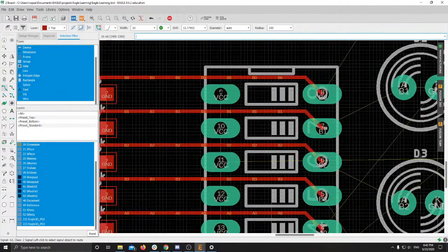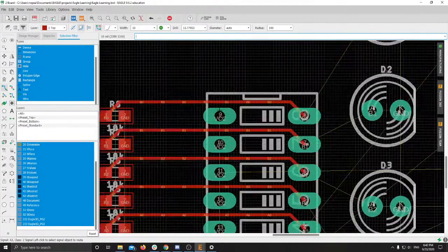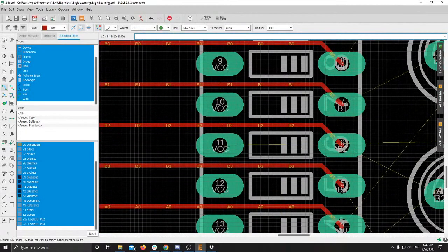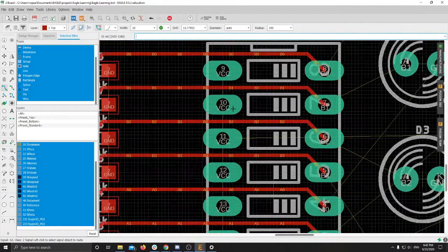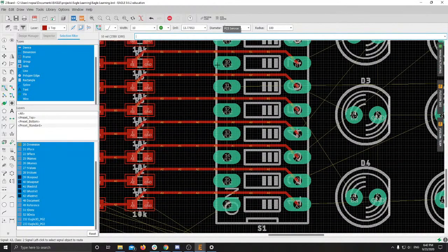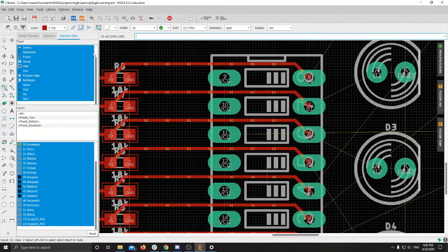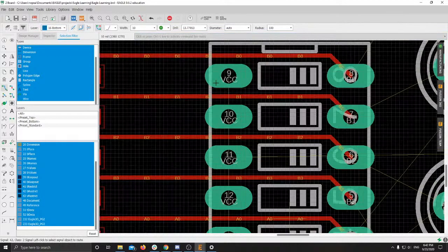So now one thing you'll notice here is, I have all these connections running in between all the DIP switch connections that are making VCC an issue. So how am I going to connect this without being able to cross under each of these? So this is where we'd use the bottom layer. Because these are through hole, it's very easy to just go right under all of them.